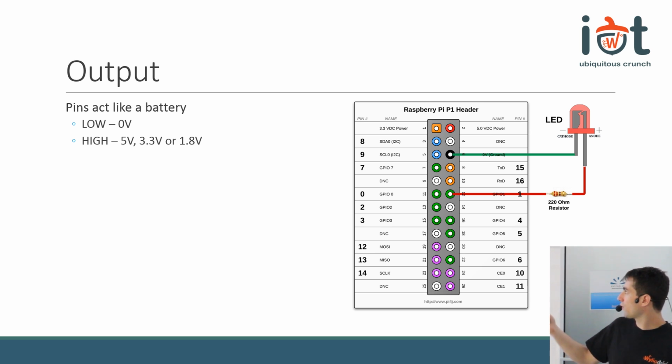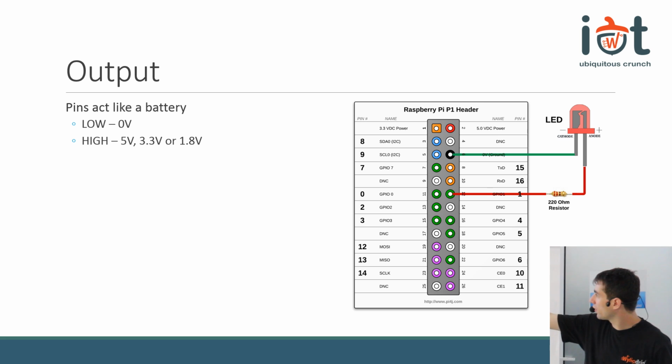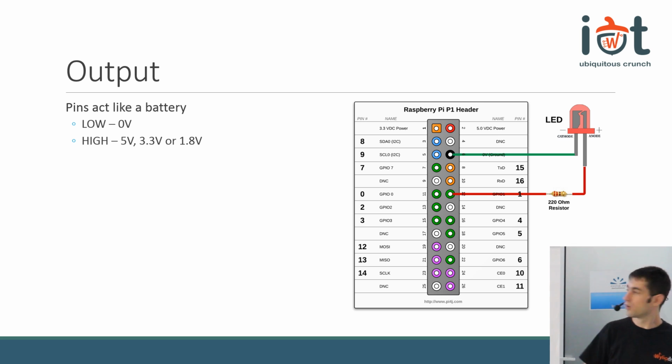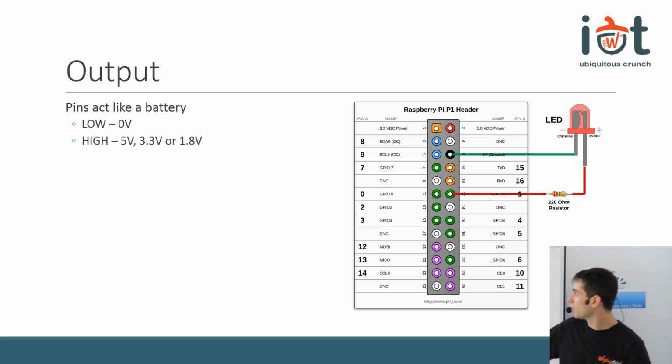In my example over here, we have an LED which is connected to the ground, and connected via a resistor to the pin. The pin is marked as output, so I can write values on the pin. If I write the value 0, what is going to be the output? If I write 0 on this pin, the voltage here will be 0. What happens with the LED?